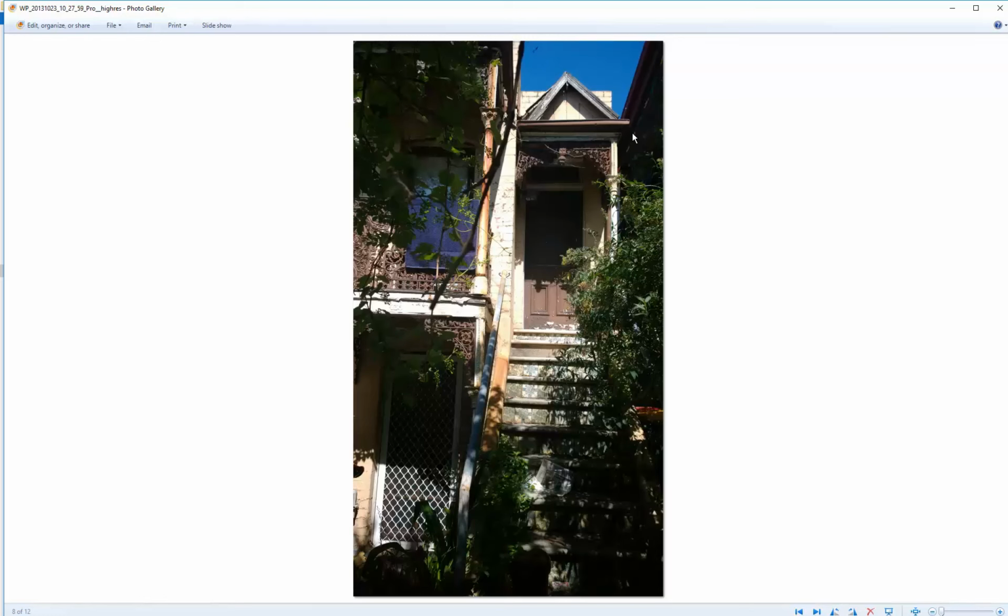I would take that off. Don't put a gutter along the front of a gable. There is no need. That is just bodgy building. It looks terrible and it's wrong. The reason it looks bad to us is because it doesn't make any sense. There's no drainage.